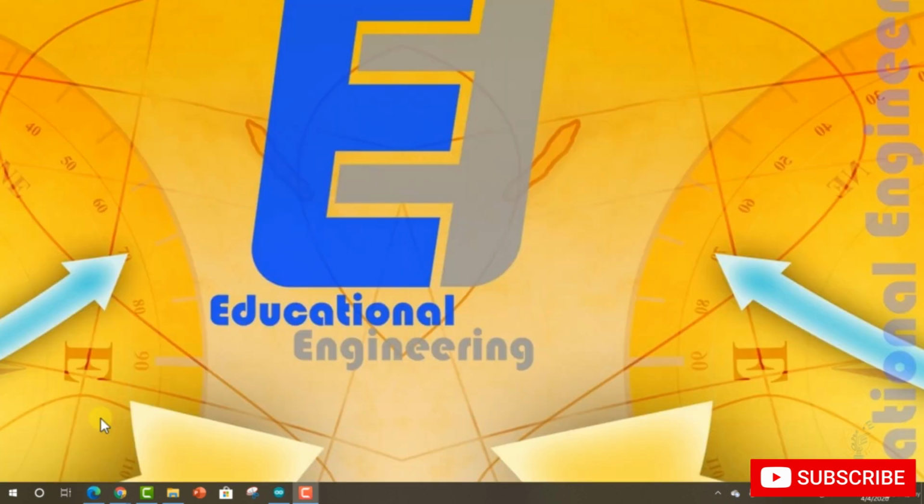Hello and welcome to the Arduino coding lesson. Before we start coding, let's explain the things that we are going to do. First, we are going to declare some pins. The LED pin, which is pin number 13, because Arduino has an internal LED at pin number 13. Also, we have to declare the sensor pin, which is pin number 2, since we connected the signal from the motion detector sensor to that pin.